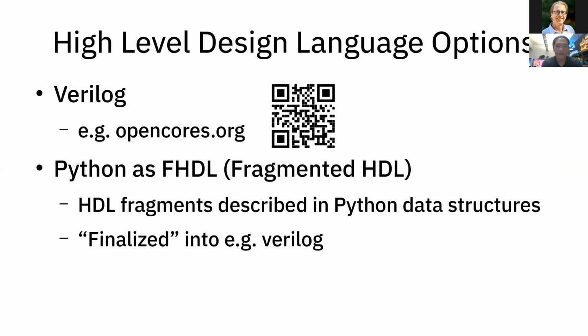But the area I've been focusing on the most is using Python as an HDL. It sounds a bit weird, but you're not literally writing Python code and compiling it to hardware. What you're doing is describing hardware as fragments of Python data structures, so they call it a fragmented HDL. Then it goes through a process of finalization, which turns it into an actual Verilog file.